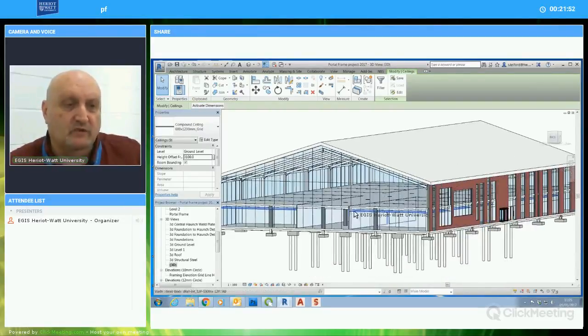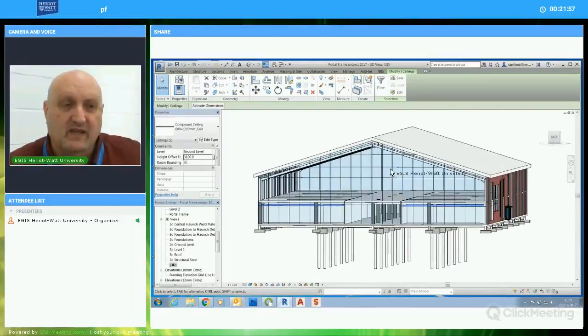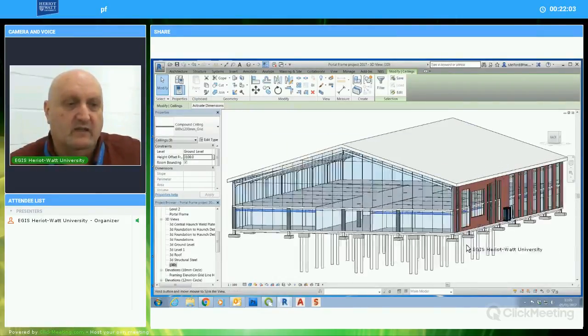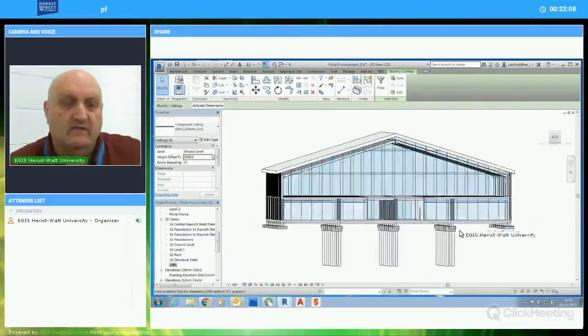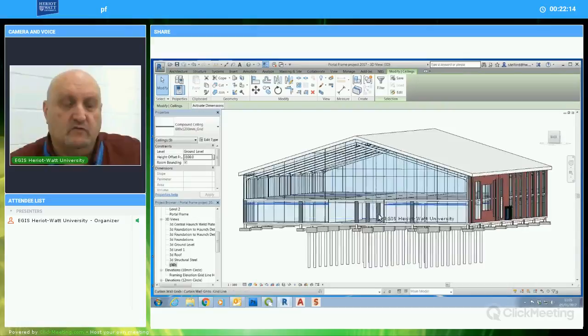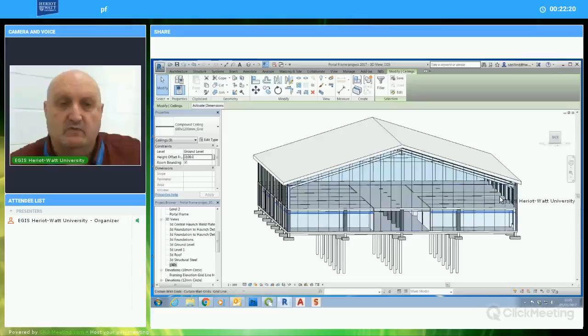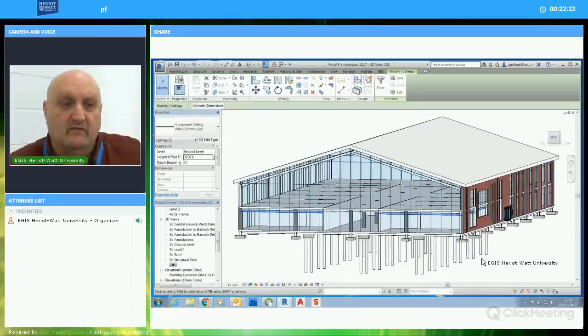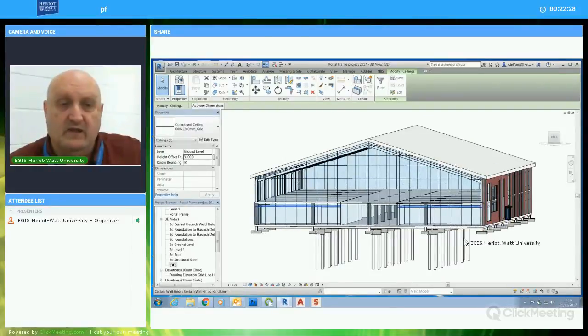And you'll notice I'm not putting ceilings on this level here. The whole point of a portal frame building is that there's a whole lot of open space up here. If you're in a shopping centre and it's this kind of construction, you'll see that often there isn't a floor here at all. We've put this in here to let you see the difference between this busy area down here with a whole lot of columns, structural columns covered in architectural columns and walls and things, and the kind of open space that the portal frame allows you to have on the floor above. But often there is no floor above, it's just a single floor, a massive open space that the portal frame permits you to have.